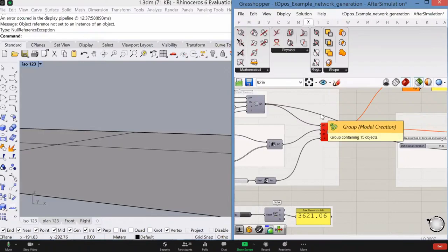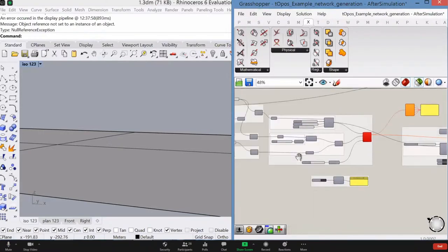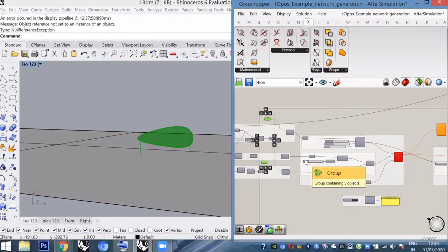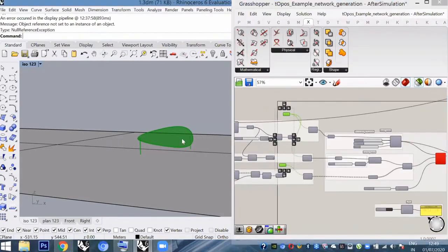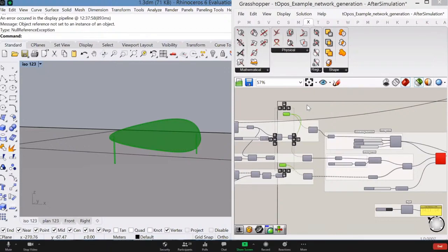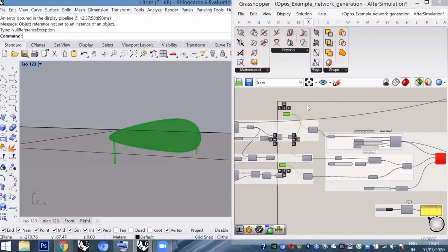Can you show the input geometry? Mainly it's because the input geometry has no intersection or doesn't have enough intersection, so there's no element in the columns or no elements for the loading. The two elements I have given, the boundary domain and the supports, are actually not intersecting. They're just touching each other. So maybe I will try intersecting both of them and do it once again.